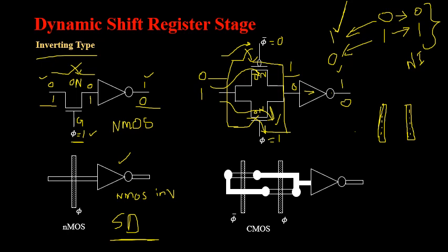Next, two transistors are supposed to be formed. One of P MOSFET, if I assume this as P MOSFET, I will assume this as N MOSFET. So this blank layer is nothing but a diffusion. So if it is a PMOS, this is P type of diffusion. If this is NMOS, it is an N type of diffusion.